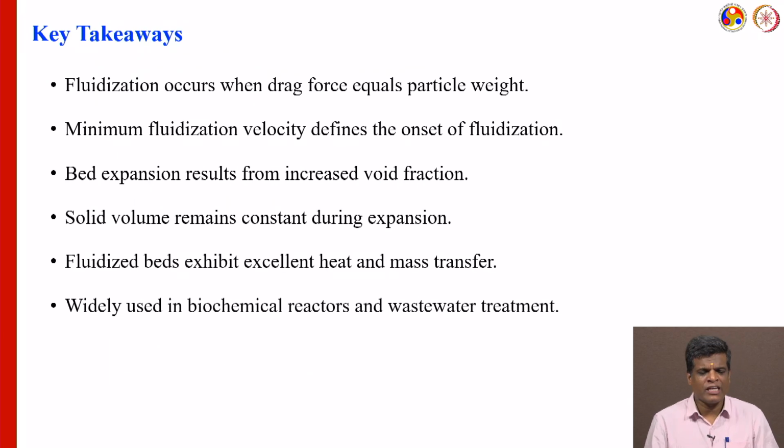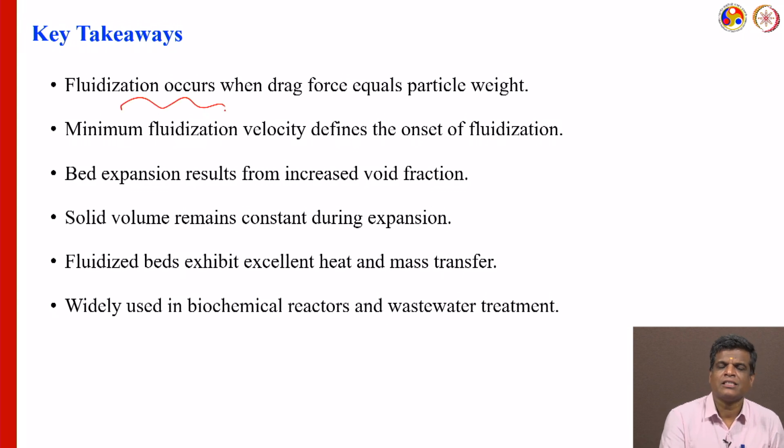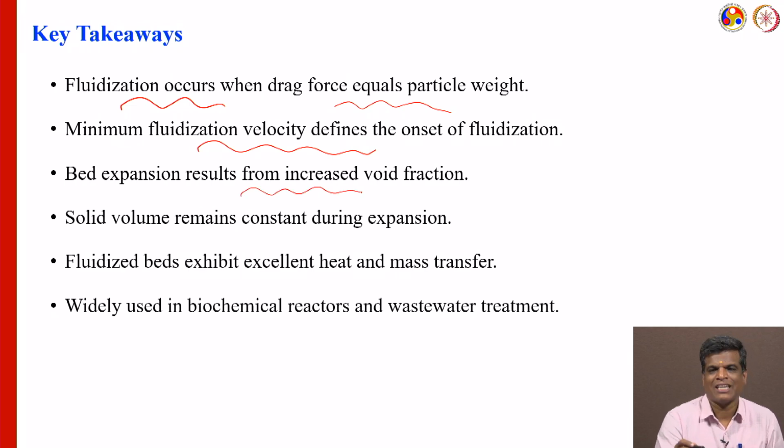So, what are the key takeaways here? Whenever fluidization occurs, there is a drag force equal to the particle weight; that is called the minimum fluidization velocity. The minimum fluidization velocity we discussed. The bed expansion results from increased void fraction. So, as the void fraction increases, the bed expansion also increases.